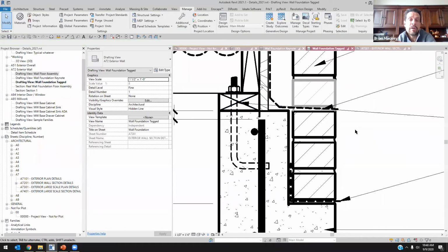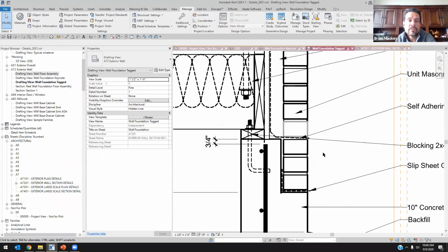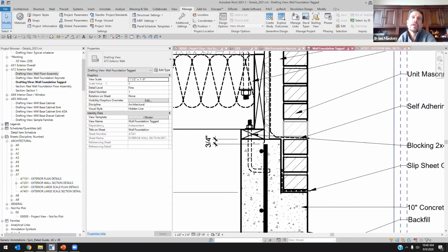I am absolutely a person who thinks things in Revit should be more color coded based off of data. My code plans are all color coded. I do wall heights that are all color coded. I do a lot of color coding with clients. I believe color should be there based off of data, not just be there because you want it to look like AutoCAD. So yes, I absolutely go through and set that up and use colors for things. That's just going to depend on what you're looking at and the type of people you have.